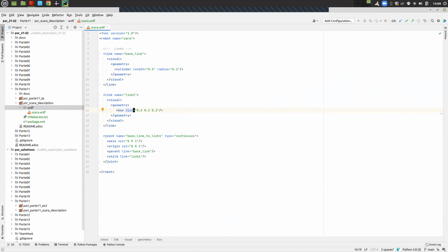Sure, Manel. In the GUI that we have, what if the joint has more than 1 degree of freedom? There is no joint which has more than 1 degree of freedom. So there are two types of joints. Prismatic. Prismatics move over 1 degree of freedom. Then you have the revolute, which rotates around one axis. Then theoretically you can have a spherical joint. Those have more than 1 degree of freedom, but I don't think they are supported in ROS. Nor in most of the softwares I know, I think. This is just a theoretical concept.